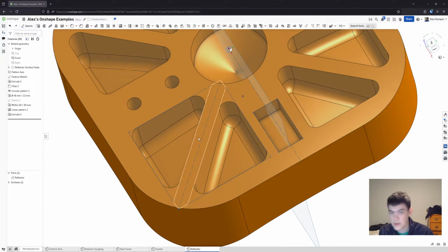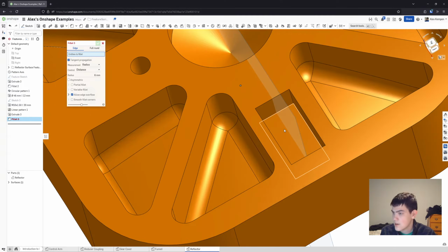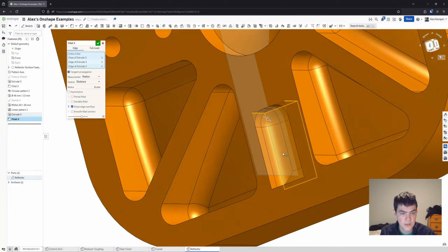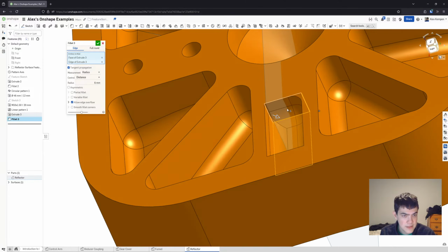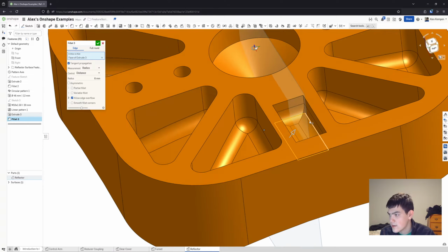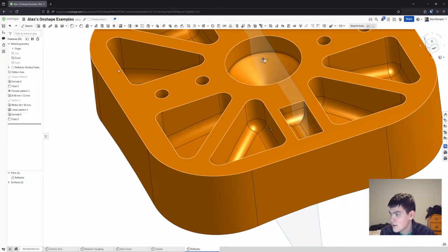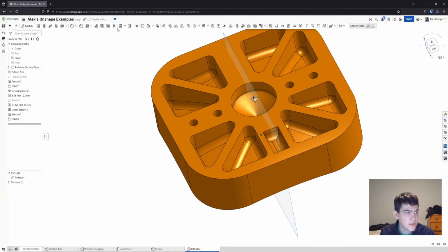Yeah, so that's good, and then we're going to fillet this as well. So I'll hide this sketch, and I can select this face, and then I can select these edges as well. Don't forget to select those. Oh, actually I don't have to. I can just click the bottom face and it'll grab all those edges, which is good, and this is going to be a 6mm fillet, which we already have set. Cool, so we'll go ahead and set that. And then we're going to mirror this.